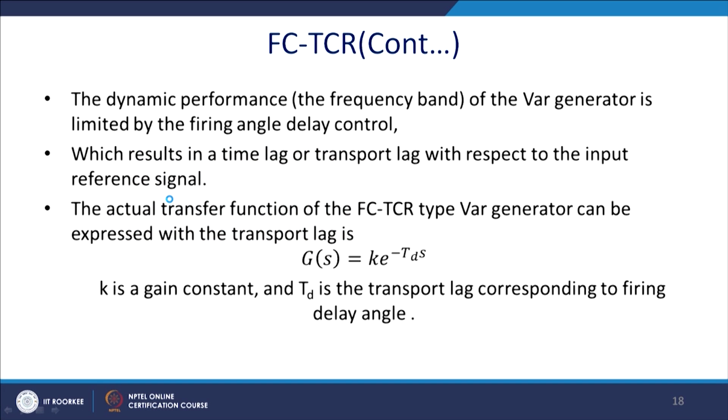So, what happens here is that the dynamic performance, the frequency band of the Var generation, is limited by the firing angle delay control. It will take a delay, because once you have calculated, you are allowed to trigger the thyristors only after a certain interval of time.